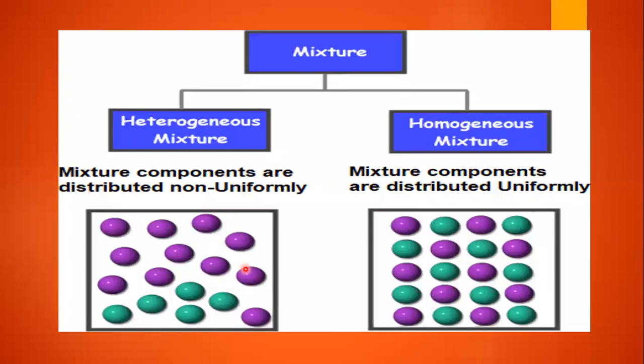If wastage of fuel is there, remember we are going to send only the amount which is required. So if it is lost on the piston head and cylinder walls, there may not be sufficient fuel for complete combustion. That's why we need to maintain high density for the air. That means we need to increase pressure and temperature as much as possible.